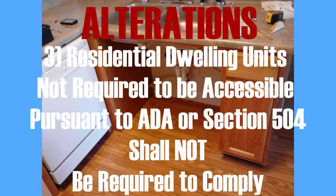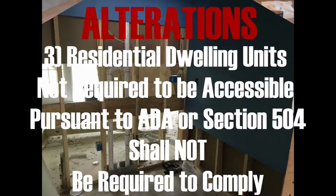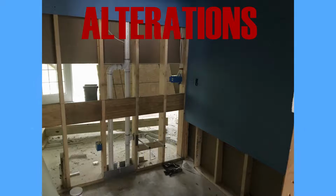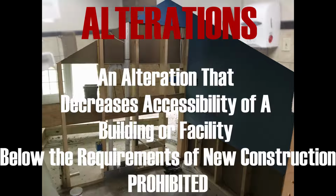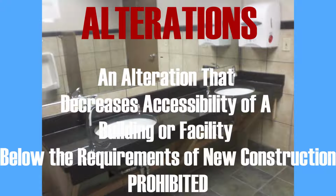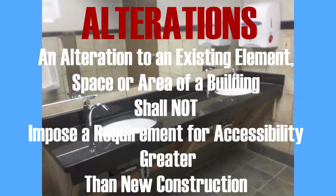feasible. Residential dwelling units not required to be accessible pursuant to ADA or Section 504 shall not be required to comply with these standards. An alteration that reduces or decreases accessibility of a building or facility below the requirements of new construction is prohibited. An alteration to an existing element, space, or area of a building shall not impose a requirement for accessibility greater than new construction.